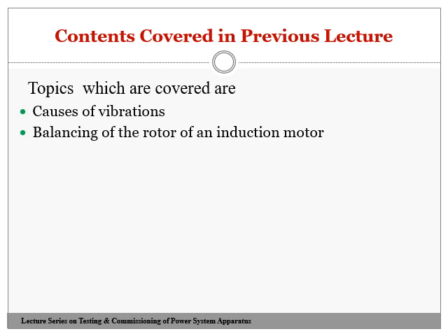And these vibrations should be suppressed with different methods after measuring with the indicating meters or vibrometers or any of the gadgets which are available in the market. Afterwards, we have seen the balancing of a rotor of an induction motor. The balancing is a must, as unbalance is one of the causes of vibration in an induction motor. If the vibration becomes more than the specified permissible limit, it may cause damage to the rotor as well as the shaft and the bearing gears. That's why the balancing of a rotor comes into the picture.